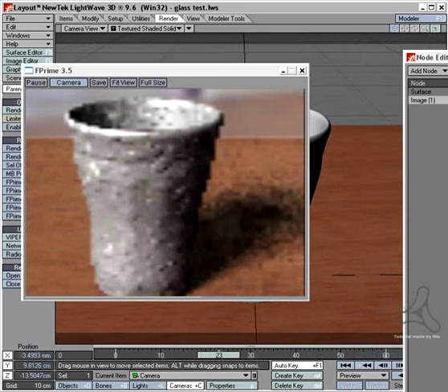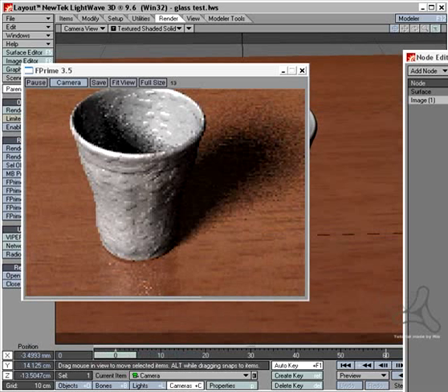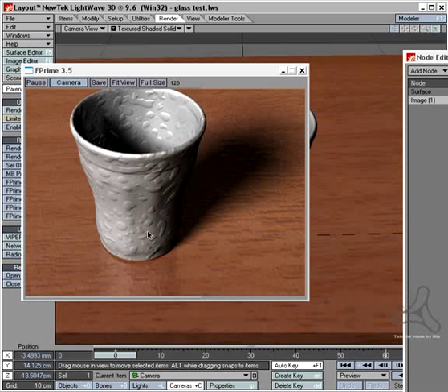However, what you see also is the problem that I was referring to before, that the bump map is both on the inside and on the outside of the glass, which is not exactly what I need. The problem is that later I'm going to set up some glass texture on the glass, and the entire object would have the same surface. So how do I change this so that my bump map is only available on the outside of the glass? I can use weight maps for that, and I'm going to show you how.